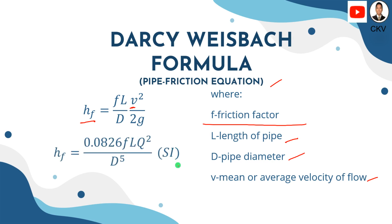So if we are going to use the discharge, here's the equivalent formula for the head loss using Darcy-Weisbach. So that's equals to 0.0826 f L Q squared over D raised to 5. So this is in SI units.